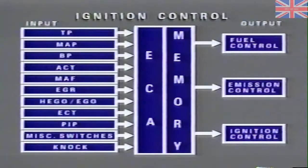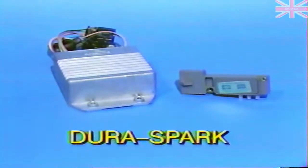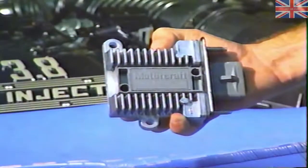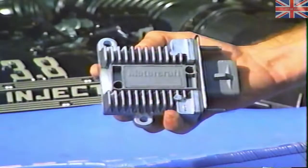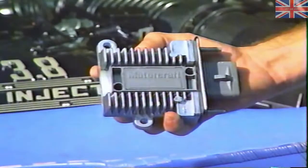Since this program deals primarily with the EEC system as a function of ignition or timing control, the output of the engine control computer will be to either a DuraSpark ignition module or the TFI, Thick Film Integrated Ignition Module. Beginning around 1983, the thick film ignition system was introduced on the 1.6 and 2.3 liter engines and has since been used across all engine configurations since 1988.